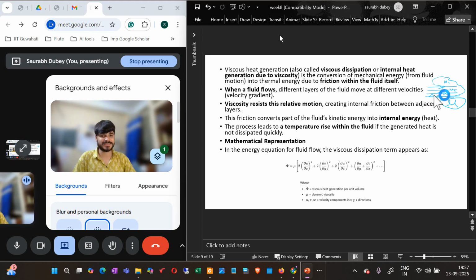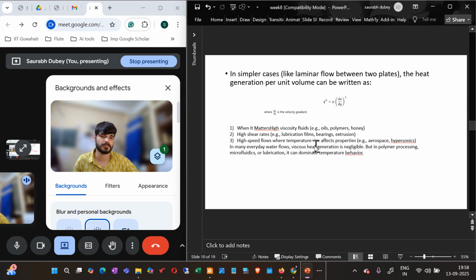so you can see the unit of it: u is meter per second, x is meter. So here per second square, and then outside is Pascal second. So Pascal per second comes out, and Pascal is what? Force per unit area, right? So based on that, you can convert to Newton per meter square second. Okay. So on units also you can be asked some questions.